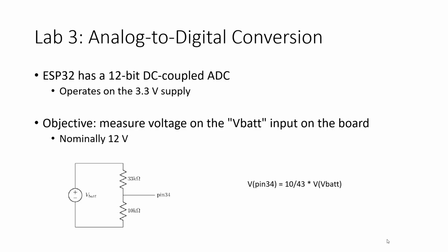But we have an issue because you cannot read a 12-volt signal with a 3.3-volt analog to digital converter. So we put in a voltage divider. Do you guys remember voltage dividers from Circuits 1? A voltage divider converts one voltage to another, but it does so wildly inefficiently, because it does it just by wasting power, sinking current unnecessarily through a resistor and heating it up for no purpose whatsoever. It's a very simple circuit though.